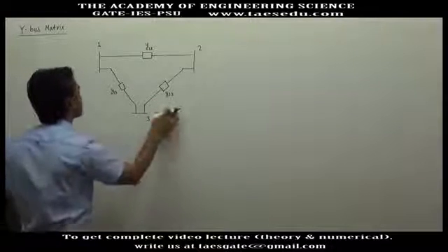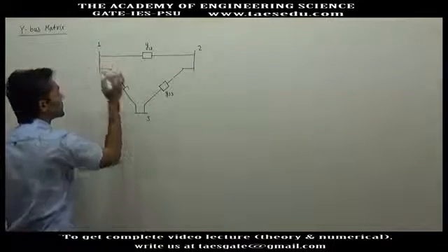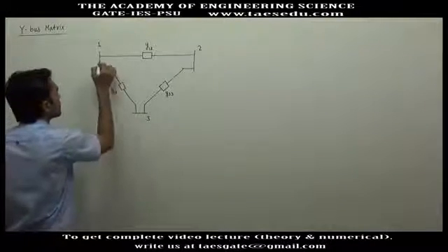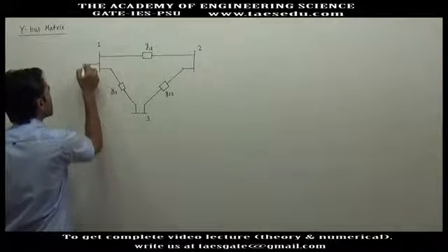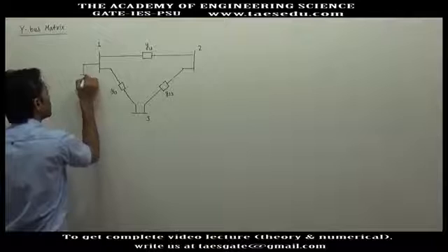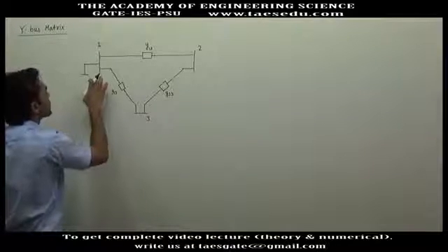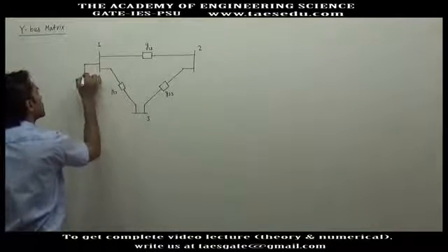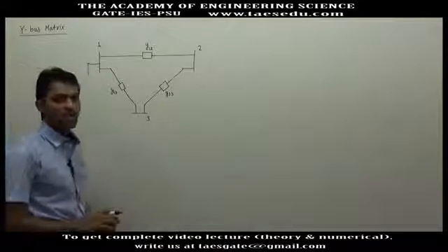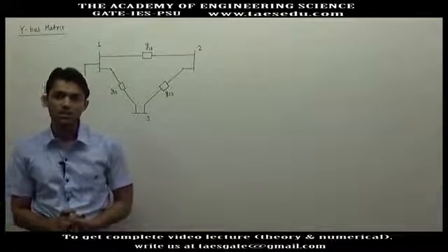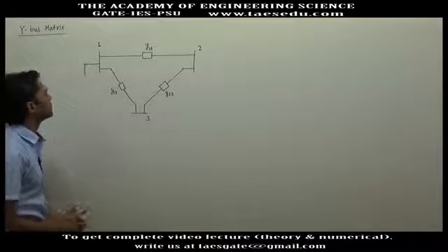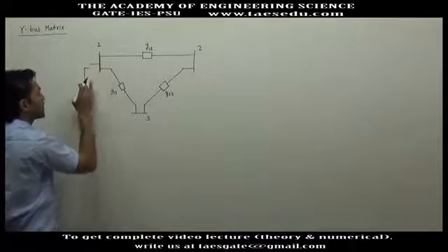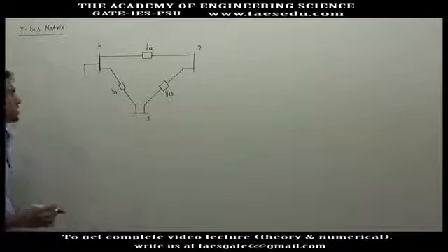So apart from these admittances, it is not necessary that only these exist, some buses also have shunt elements. For voltage control, we connect a shunt capacitor to boost the voltage. Or to avoid the Ferranti effect, we connect a shunt inductor. Shunt inductor means from the bus you connect an inductor and connect the other terminal of the inductor to ground.